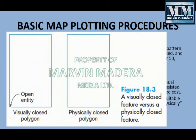So take for example, there are times that we are making a map or a figure in the CAD system. We can have this visually closed polygon, but actually the entity there is open. The end sides and points are not closed. So take note of that one. Compare this with the physically closed polygon, where all of the corners are joined together, no?